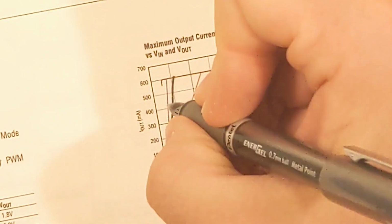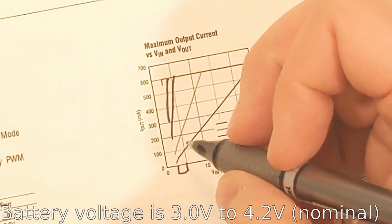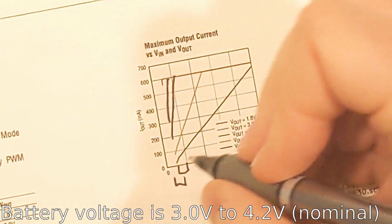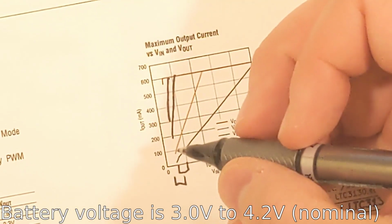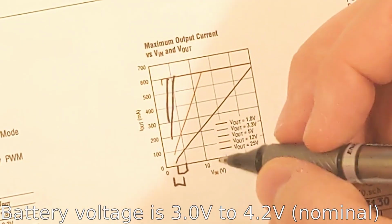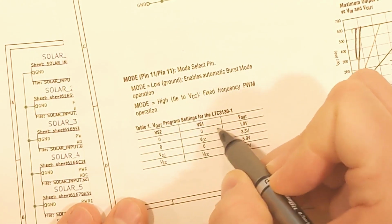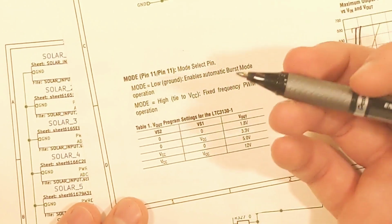For 3.3 volts, we're working with this line over here. When I get to it on the other side of the schematic, we're going to be input from the battery voltage, which works in this sort of range, and the maximum output current that I would expect that 3.3 volt converter to draw is 300 milliamps, and so we're right within that range as well, so no problems there. Oh, and real briefly, here are these VS2 and VS1 output settings, so in theory I could output 1.8 volts up to 12 volts if I really wanted to.